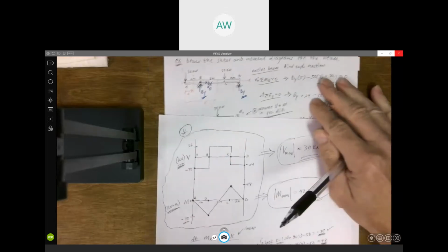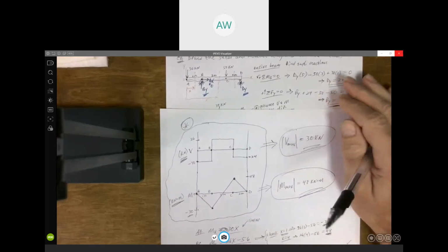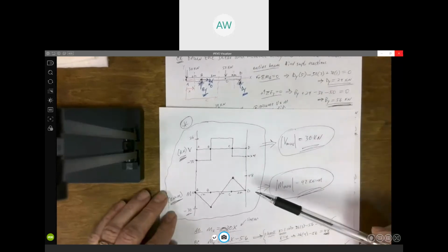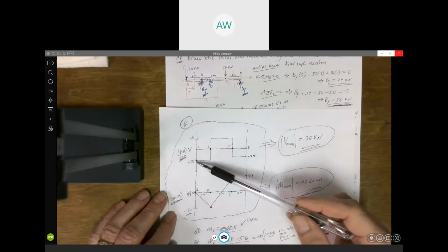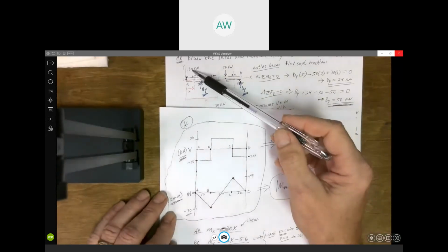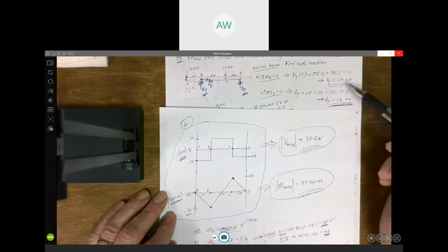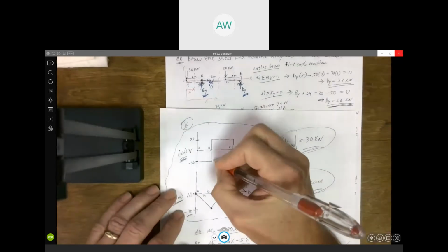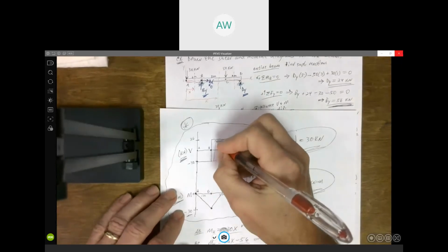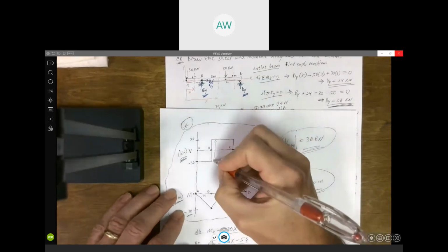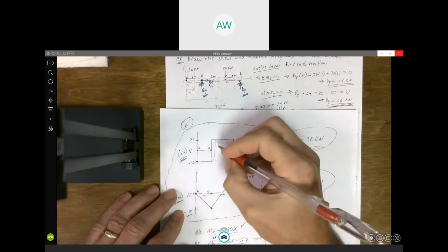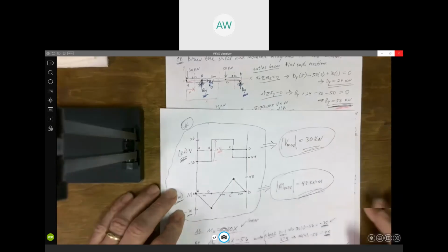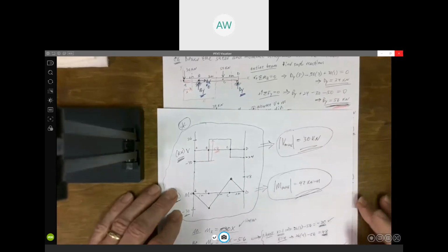In fact, last thing, just an observation. If you look at this beam, look at our shear diagram. Where do we start at here? 30. What's that force? 30. What was By? 56. What did we do at B? It's just a preview ahead of what we're going to talk about Monday. If we go from minus 30 to 26, what is that? 56. Not a coincidence.